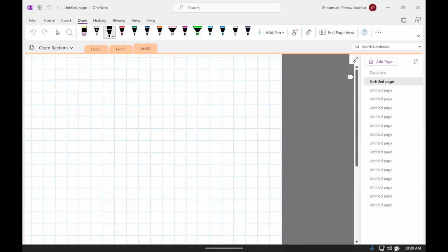Okay, next step is to compute the kinetic energy T. That would be half m times x dot squared plus y dot squared plus z dot squared, plus half omega transpose I omega. Why did I write this like this? Well, omega is 3 by 1. Omega transpose is 1 by 3. The inertia matrix, now that we are talking about the inertia of a 3D object, is going to be 3 by 3.